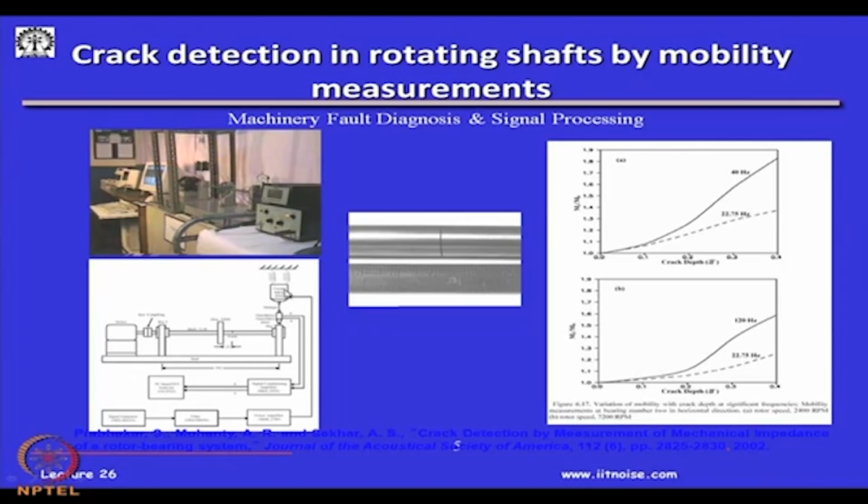So, what we had is an exciter. You see this black one here is an exciter, and with this exciter we are giving a force signal. The exciter is exciting the structure, and here we have an impedance head. Impedance head is a transducer, as I told you, which has a force gauge and an accelerometer together. So, I measure the acceleration of this system and the force being applied. This acceleration will be single integrated to get the velocity. So, I know the velocity, I know the force to this system, and thus I know the mobility.